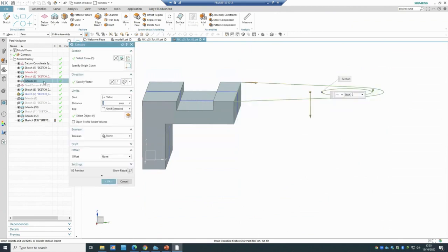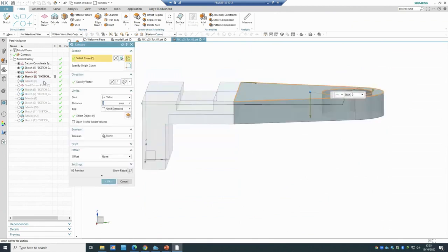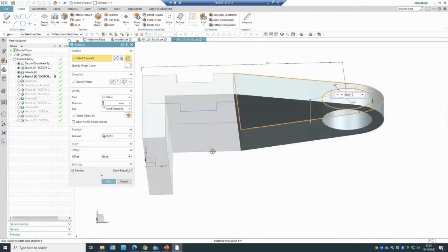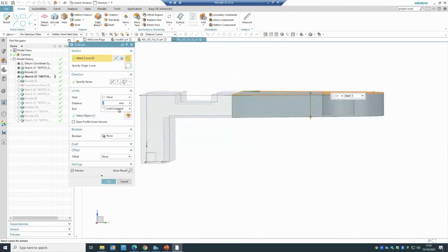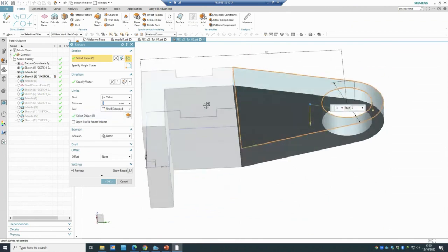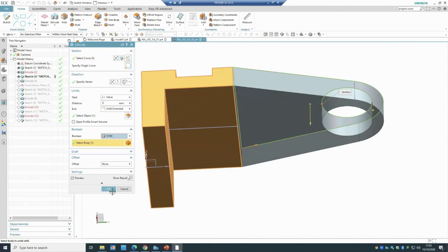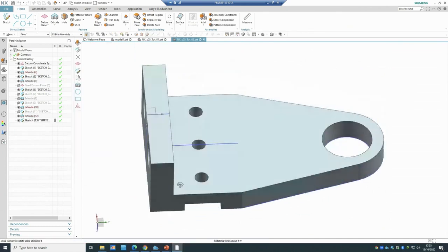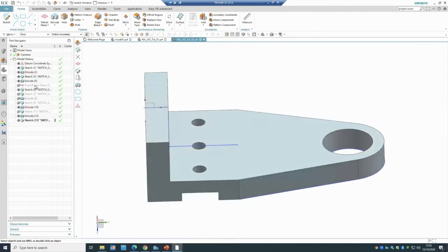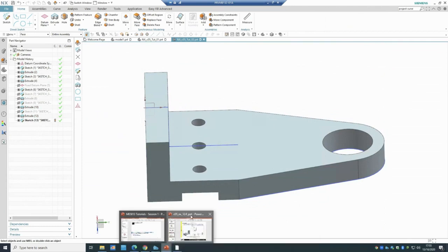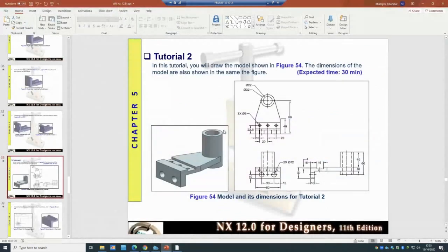You can either put a dimension, you can say you're gonna extrude it with the extrude of the 30 or whatever that was the length, or of course, the easy one, right? Then you just put extrude. You can say until extended or until selected, and just pick that plane which is there, and you have it. Make sure you click on unite, so both of them will add together. Then the other part, which is the important one in here, is how you'll be able to create this one.